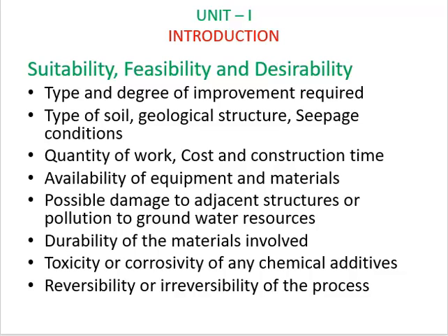The next point is type of soil, geological structure, seepage conditions. If it is coarse-grained soil, then mechanical modification is sufficient to increase the density. If it is fine-grained soil, then hydraulic modification is required to accelerate the consolidation. If it is contaminated soil, chemical modification is required. So, depending on the soil type, we have to choose the suitable modification technique.